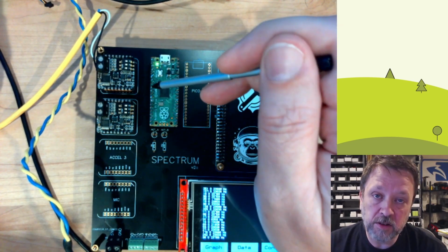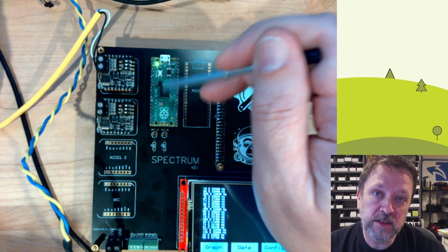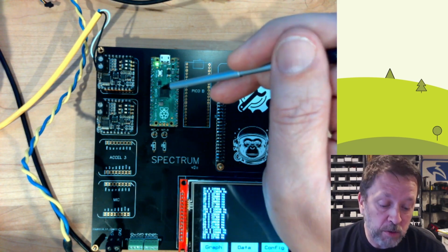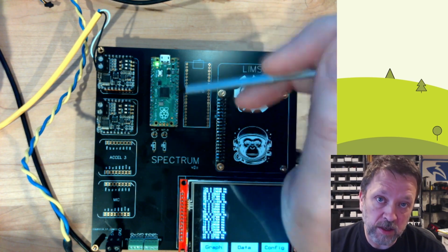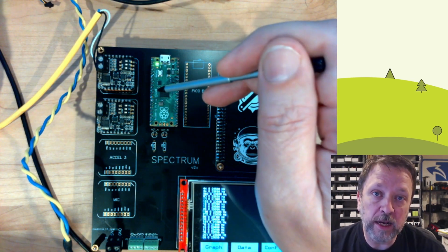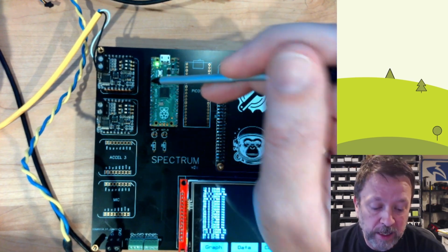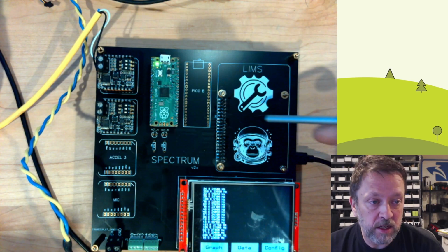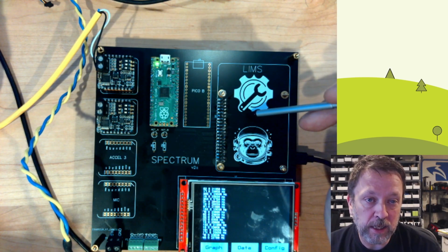And then the second core of the processor takes that FFT output. So it's really just looking at frequency and magnitude of the buckets in the FFT, and it ships those out as a continuous stream over a serial port. That serial port is then connected over to the Raspberry Pi.